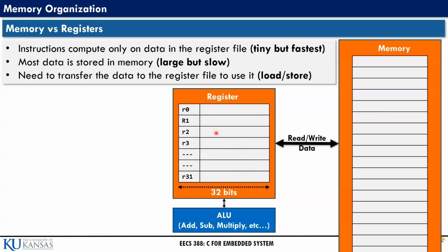So first of all, these CPU registers are designed to be accessed at very high speeds because we want to run our instructions as fast as we can, and larger registers would take longer to read and write because of increased capacitance and the physical distances that the signals must travel. These would potentially slow down the processing speed.